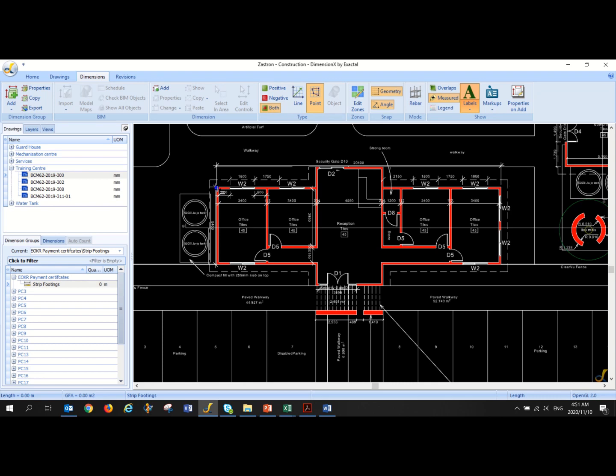So if we go to our earthworks, we basically measure the amount of work that's done. So usually you've got a set of photos and some measurements that you've done. For instance, you might have the measurements of the depth of the actual excavations, the width of the actual excavations, etc.